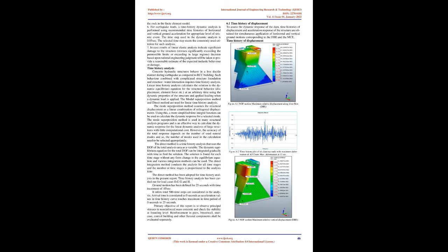5.2 Applied loads. The following loads have been considered for 3D finite element analysis of the dam blocks. Dead load, self-weight of the structure. Self-weight of structure is automatically incorporated in MIDAS. Deformation behavior of NOF block for self-weight. Fig 5.6 Deformation behavior of block for self-weight.